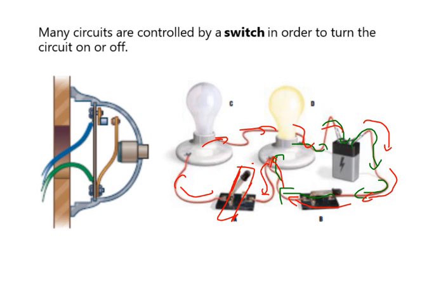Okay, here's another example of a switch that maybe works on a bit of a different principle, but this is worth looking at as well. This is a doorbell, just a basic doorbell. Right? And what actually ends up happening in some switches is that they're always set in a permanently off position until you do something to move them to an on position. Okay, so look, here is a wire coming in right there, and here is a wire coming in right here. Okay, and this little piece right here, the one that I'm drawing in red, it's meant to be the last connection. So electrons are supposed to come in here. They're supposed to go back through here. And can you guys see how there's just a little bitty gap right there where I drew that? So therefore, there's no circuit.